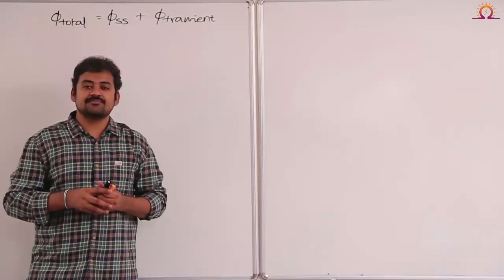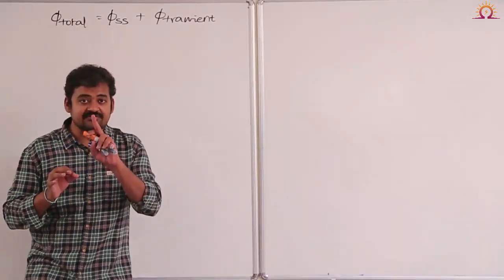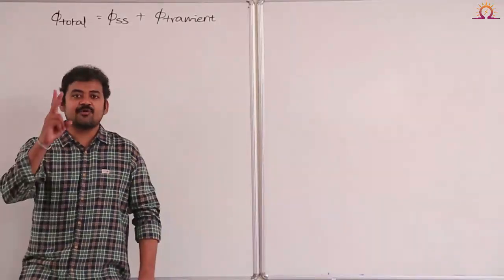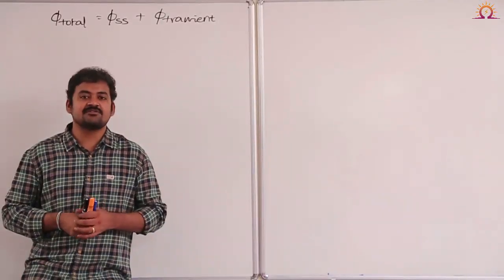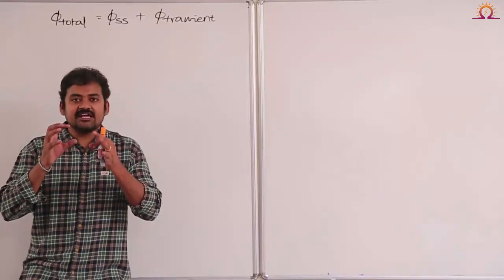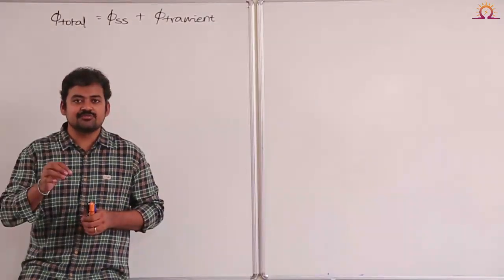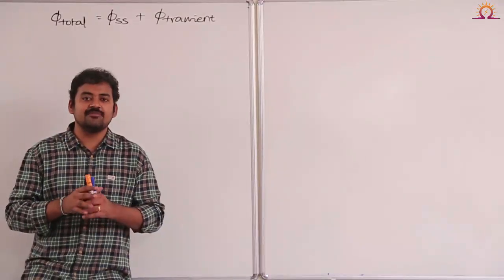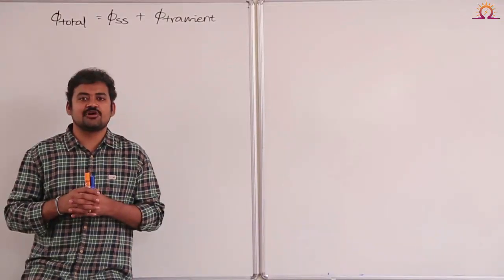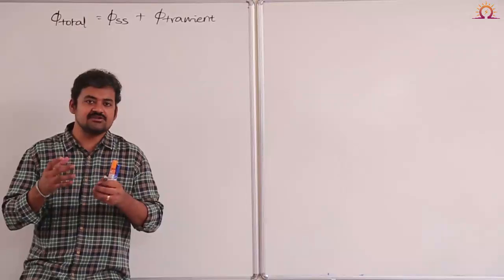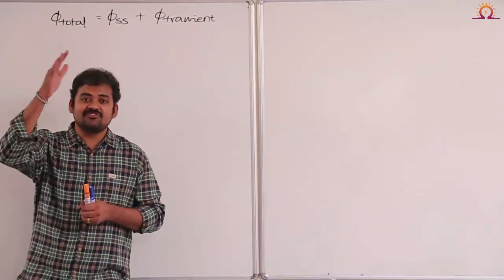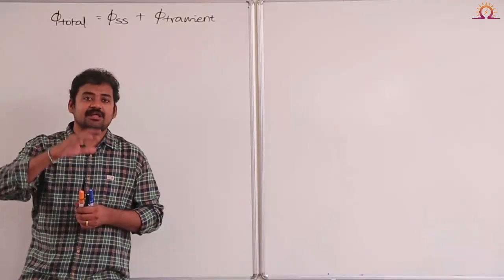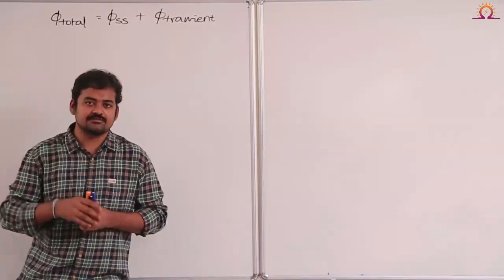The first one is, let us assume, please listen very carefully, this is theoretical concept, very important. We will be discussing about two switching in transient conditions. First one is, at the time of switching, assume supply voltage is crossing its zero value, because you tell me one thing, transformer is switched on from AC voltage or DC voltage? AC voltage. As it is a time varying voltage source, you don't know what is the value of supply voltage at the time of switching.